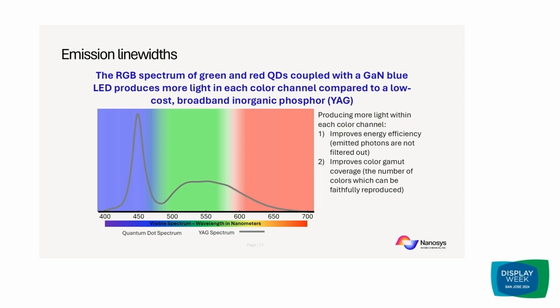Again, at their very heart, controllable emission spectra are what makes quantum dots such a revolutionary optical material and gives them so much power in displays. Based on the electronics of color coding, the way in which we run displays today is with blue, green, and red channels that we recombine to create the rest of the colors of the display.